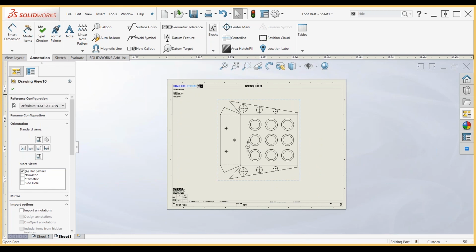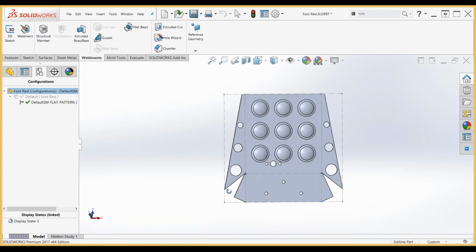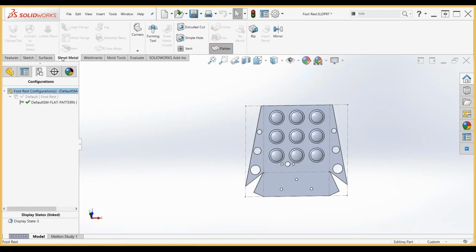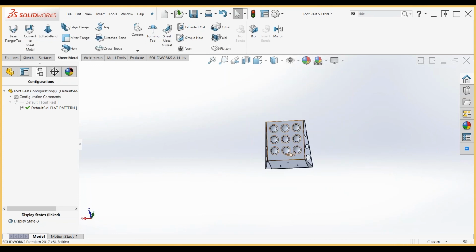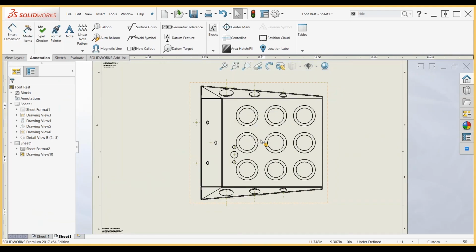So I'd open my hide show annotations and just click on all those, or box select them or something and right click and hide to hide all of those annotations. So that's a reversible process. There's also the option to convert the view to a sketch. So this is irreversible. What that's going to do is take all of these model edges and convert them to sketch entities. So I can have them as a block and keep the relative distance between them constant.